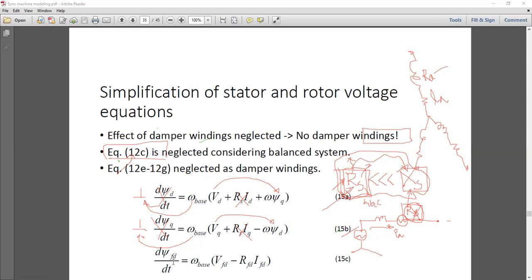The field circuit dynamics will be obtained later on. We'll model it. How are we going to achieve these dynamics? For that, we have to go through the excitation system modeling. That's the next target. We are doing the generator part now. Later on, we will go through the excitation system. That excitation system will give us this d psi FD over dt, this psi FD and its variation.